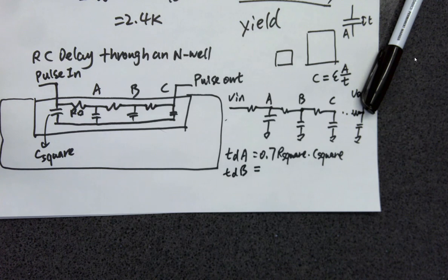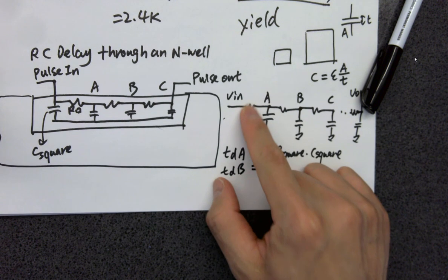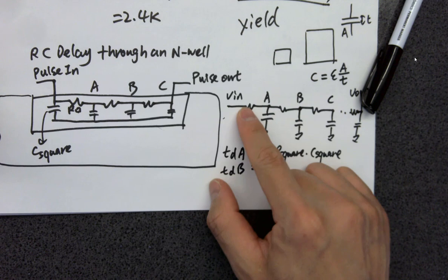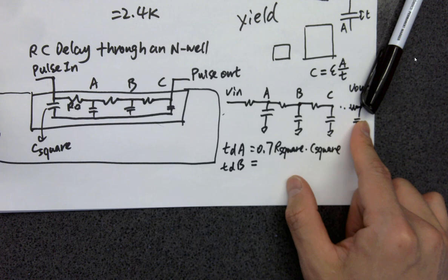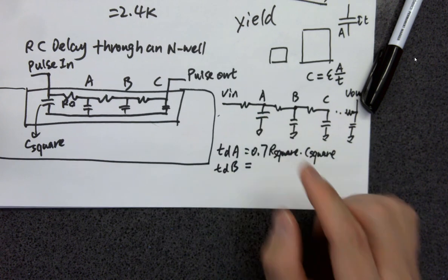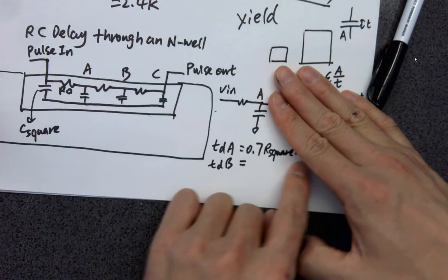So we are separating all these caps because every single cap is a bucket. You can imagine all the capacitors are buckets, and you are using water hoses to fill up the buckets with water. So these are just individual buckets hanging there, with a major hose with water in it, and these are just the hose limitations of the water flow to limit the water flow in it. But these are individual buckets holding a certain amount of water. Okay, so now let's just fill up the first water bucket. So that will be 0.7 RC.